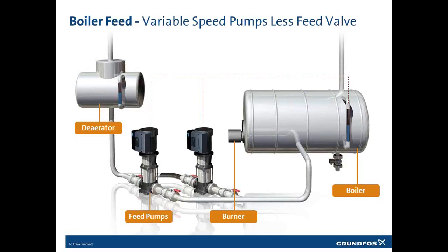Can you split one 4 to 20 signal to both frequency converters or both drives? Yes, I can do that. I need then a control box and a signal splitter. Signal splitters are produced by any major component producer, so you can get them from Schneider Electric, from Rockwell, from Siemens, you name them. They all do them, so it's an easy component to find and install.